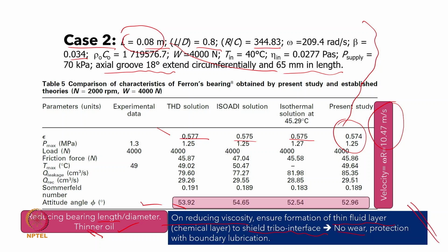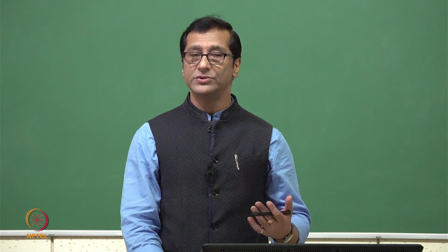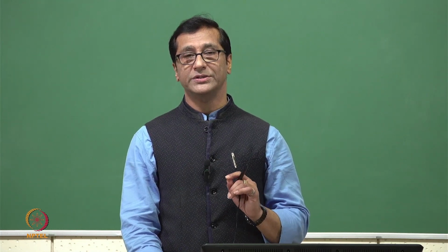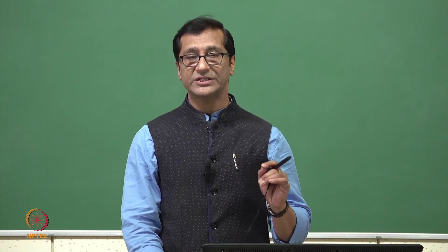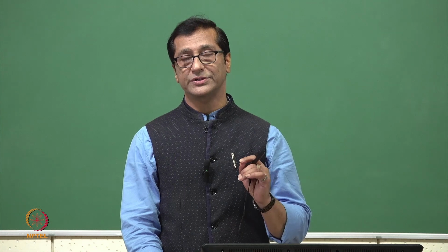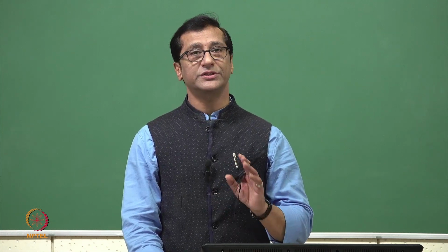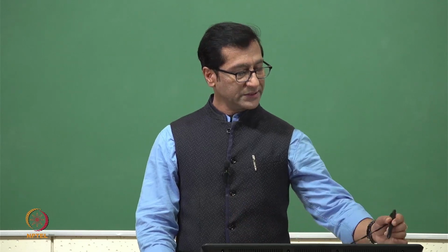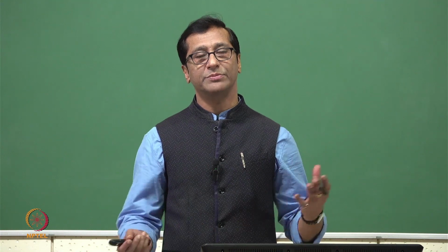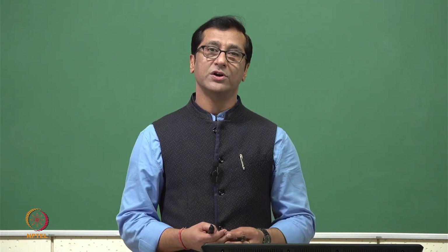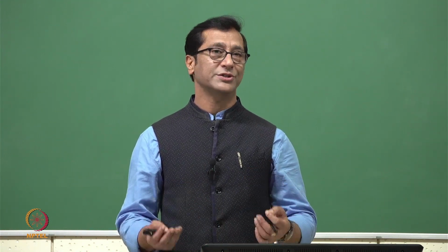So when we are talking about the design, we are saying we can reduce the oil viscosity but ensure that boundary lubrication remains intact, particularly in transient situations when we are starting the bearing, or starting the shaft and stopping the shaft. In transient situations, it is very necessary. Now I'll go further, because we have been talking about bearing design, and whenever we talk about design, optimization comes on its own.